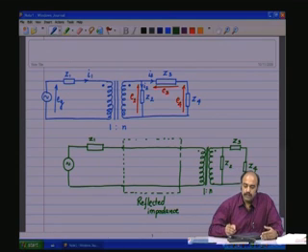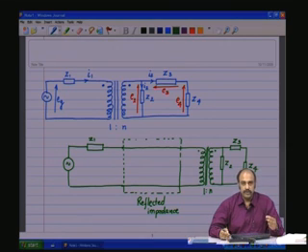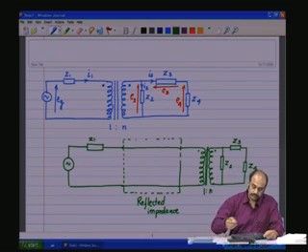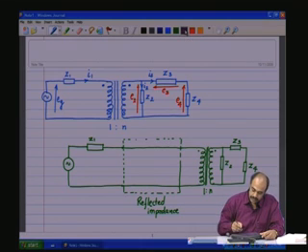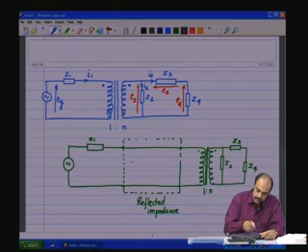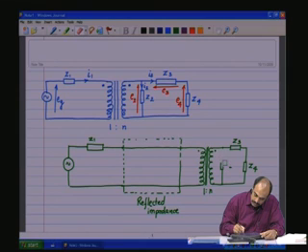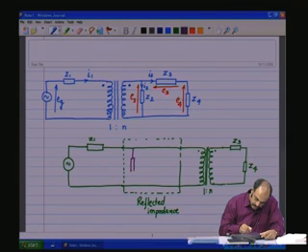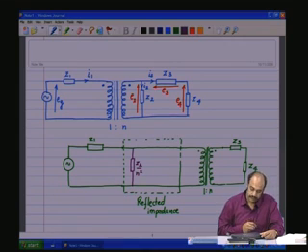So, now we want to make the impedance conversion from secondary side to the primary side, which means you have to divide by n square. So, Z2 will be transferred to the primary side. So, they can be transferred just as such. So, Z2 is removed from there and it will come in here parallel across that one. Now, it would have a value Z2 by n square.